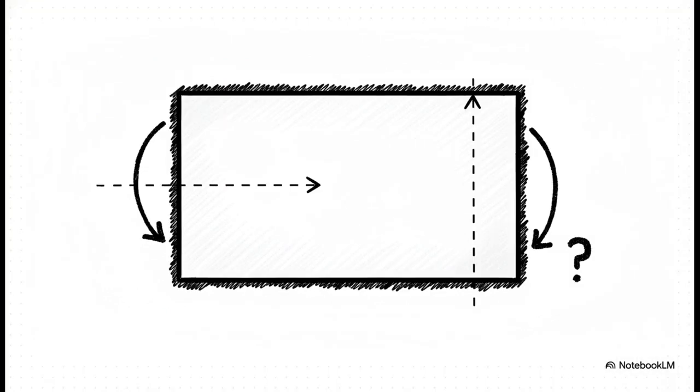So what about the vertical axis, Iyy? Easy. I've got a simple trick for this. Just remember, for any axis, the dimension that runs parallel to it is to the power of 1. The dimension that's perpendicular to it gets cubed. So for our vertical axis, d is parallel and b is perpendicular. So the formula just flips to become bd cubed over 12. This is a classic MCQ trap, so don't get caught out.